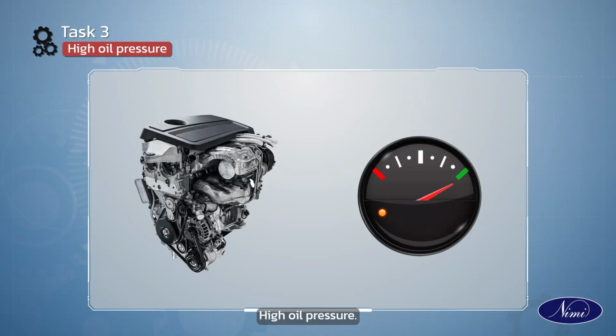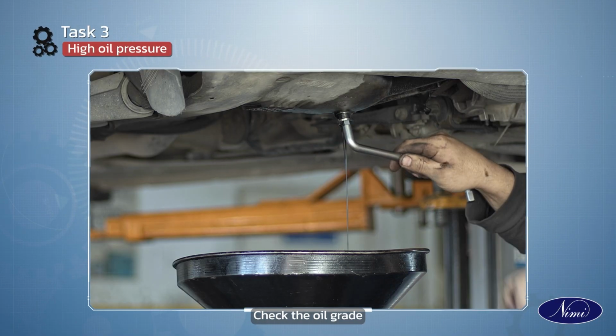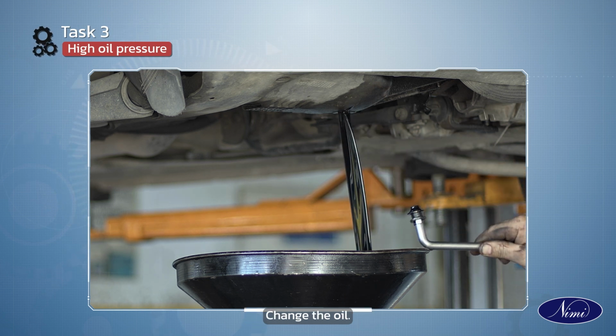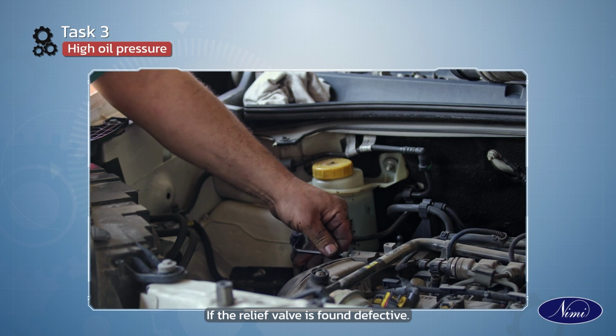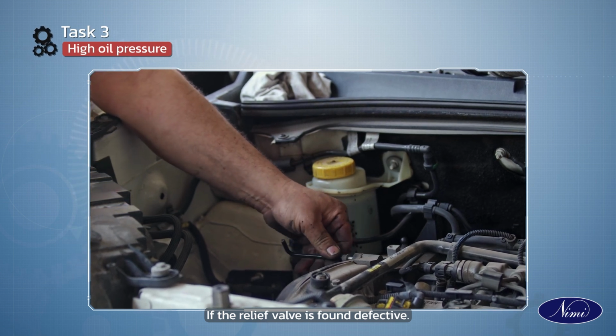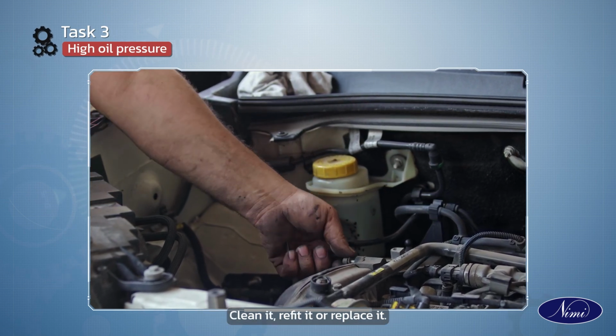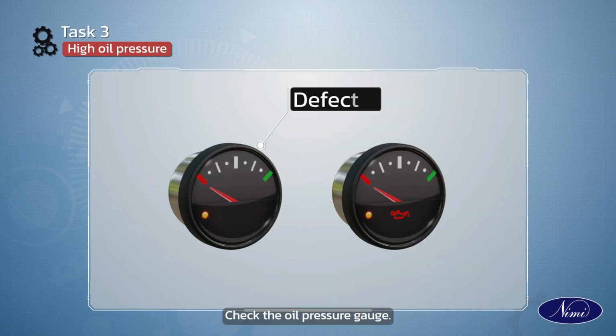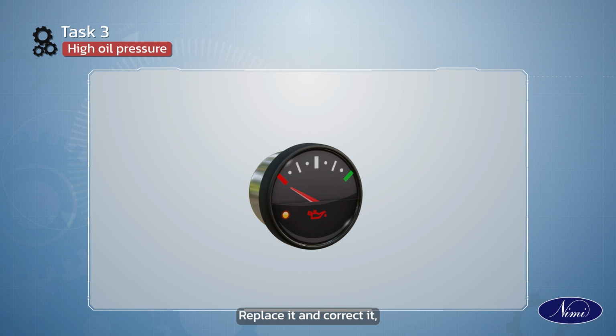High oil pressure. Check the oil grade. If the engine oil is dirty, change the oil. Check the relief valve. If the relief valve is found defective, clean it, refit it or replace it. Check the oil pressure gauge. If the gauge is defective, replace it and correct it.